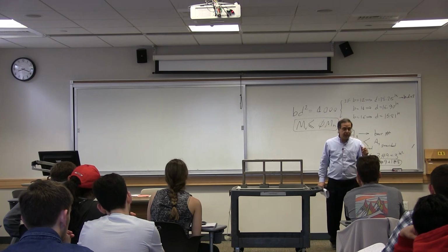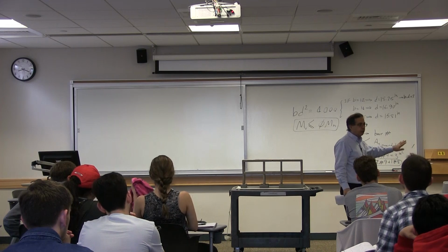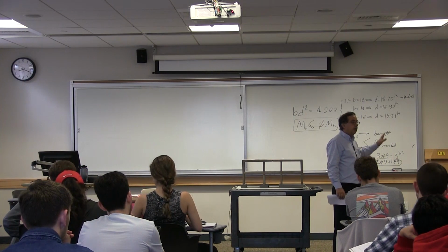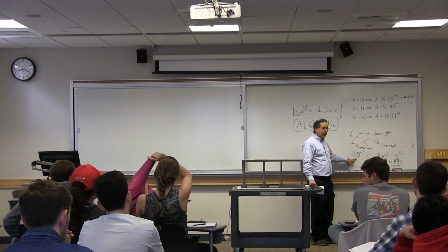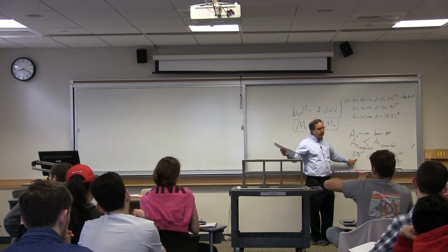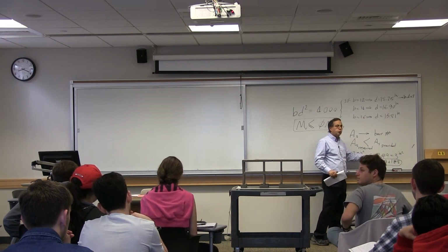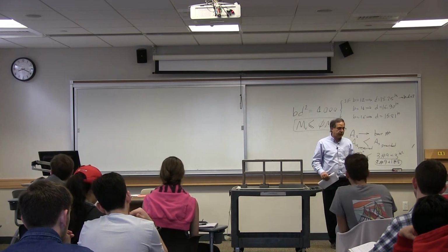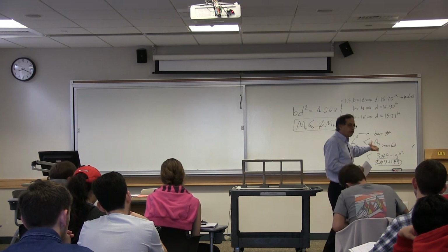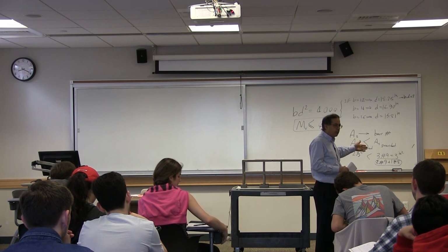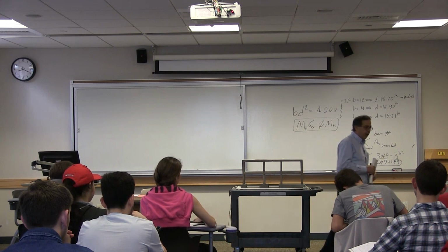Let me rephrase what I said. Do not worry too much about your area being slightly or somewhat more than the area required. We'll talk about it later on, if you have, let's say, 2.75, considering other requirements, not what we have talked about so far, but other requirements, how we choose the bars. There are other things to satisfy. At this time, just choose, I mean, this is the short story, something that is reasonably close and somewhat larger than 2.75. Now continue if I haven't answered your question yet.